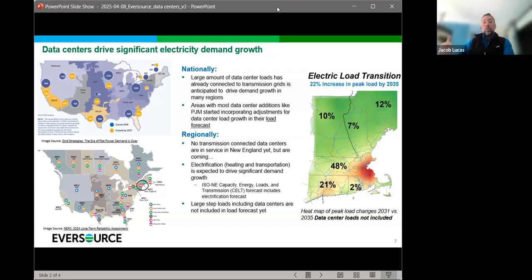And where are we going though? So already in our long-term load forecasts on the electric side, we have already pulled in adoption for electrification, both in the transportation sector and the heating sector. And that by itself is driving not only a switch of New England becoming a winter peaking system by all accounts in roughly the 2035 timeframe. That winter peak will have increased from the historical all-time of 25 gigawatts to around 40 gigawatts. And fast forward all the way to 2050, and this isn't even the fully electrified scenario, this is more of an all options kind of scenario, it's expected that New England's electric load is going to double, 25 to 50 gigawatts by 2050. And so why is that important?